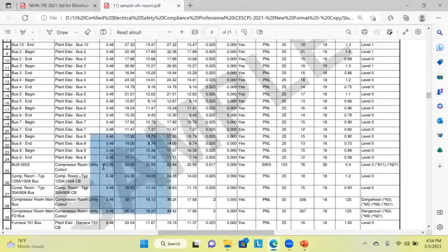For a 22 kV system, in row number 25, you see the incident energy is only 5.4 cals per centimeter square because the device clearance time is 0.017. That shows how the device clearance time, or the device tripping time or fault clearance time, has an impact on the incident energy. Okay.